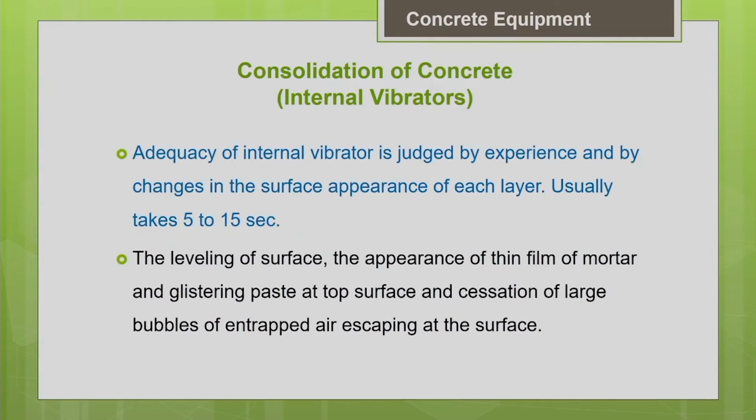So how long should I vibrate at a particular place? Usually we take approximately 5 to 15 seconds, but it depends upon the consistency of the concrete. Generally, based upon experience, the worker, by looking at the concrete surface itself, can make a guess whether the consolidation is done or not.